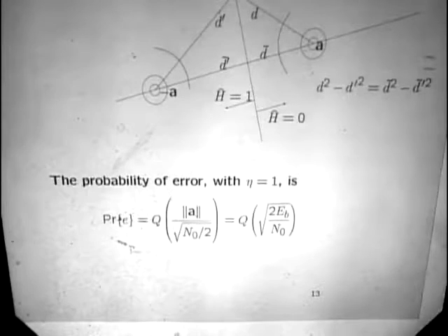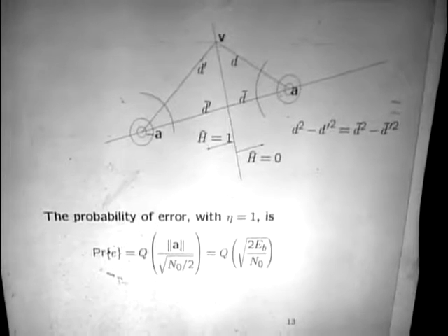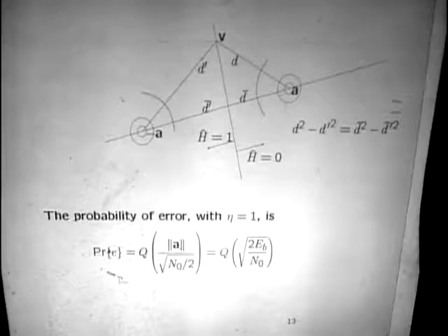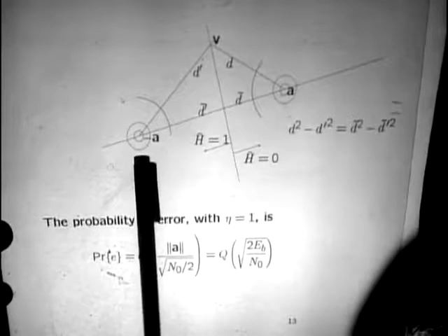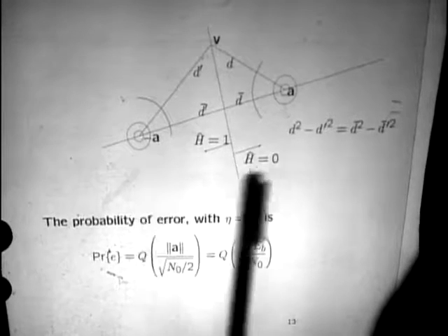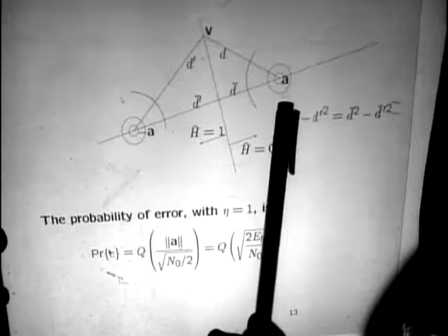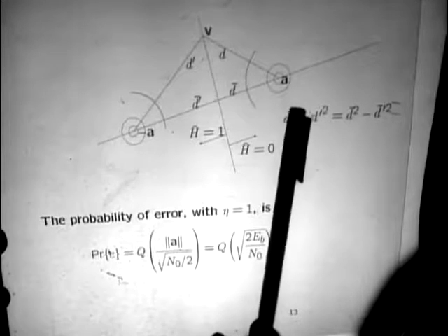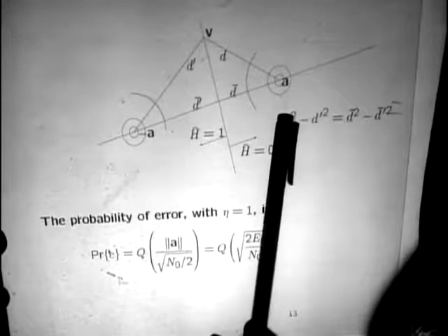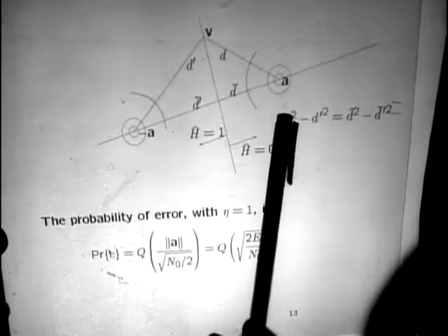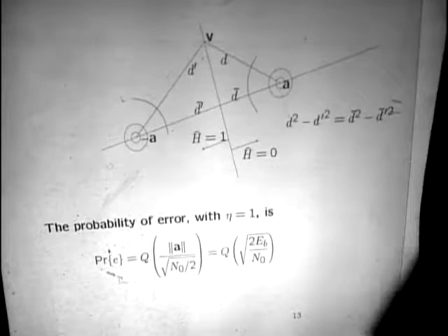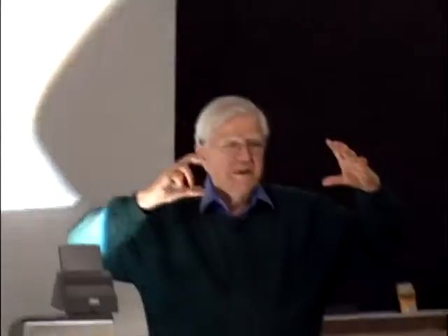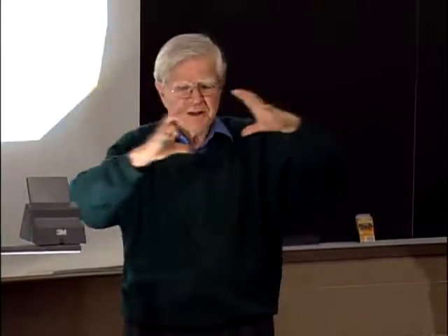Let's look at the picture that we get when we just look at the problem in two dimensions. So we're either going to transmit a vector A, or we're going to transmit a vector minus A, and think of this in two dimensions. When we transmit the vector A, we have two-dimensional noise. We've already pointed out that Gaussian noise has circular symmetry, spherical symmetry in an arbitrary number of dimensions. So you get these equal probability regions which spread out, like when you drop a rock into a pool of water. You see all of these things spreading out in circles.